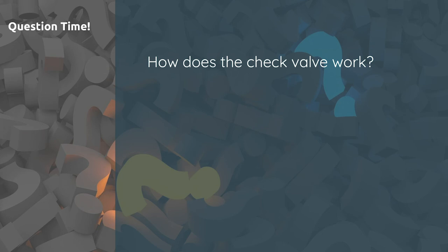So emitters have these little checks built in them to basically hold the water back. Different checks work in different fashions. For example, the threaded check, I can really talk about that one because I'm familiar with it. The threaded check has a spring-loaded stainless steel ball with a spring in there, like a true baby check, and it holds the water back upstream from that emitter. So it's holding the water in the line. And if you have other checks, an inline built in, it's checking to a certain elevation change only. Anything beyond that, it's going to release the water. So that's how it works.